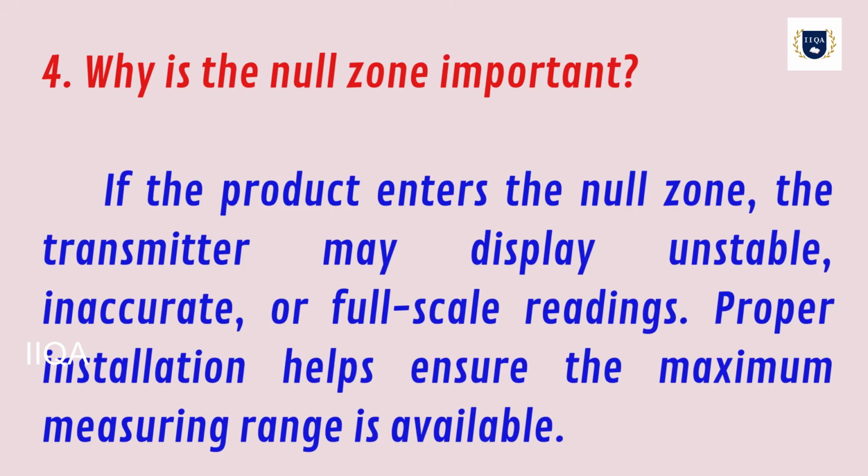Why is the null zone important? If the product enters the null zone, the transmitter may display unstable, inaccurate, or full-scale readings. Proper installation helps ensure the maximum measuring range is available.